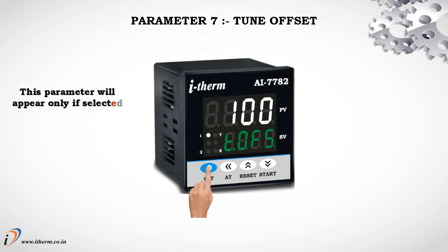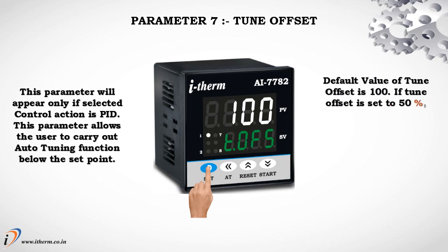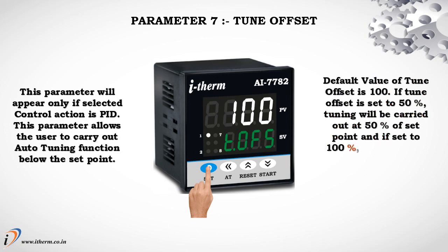Parameter 7, Tune Offset. This parameter will appear only if the selected control action is PID. This parameter allows the user to carry out the auto-tuning function below the set point. The default value of tune offset is 100. If tune offset is set to 50%, tuning will be carried out at 50% of set point, and if set to 100%, tuning will be carried out at 100% of the set point.